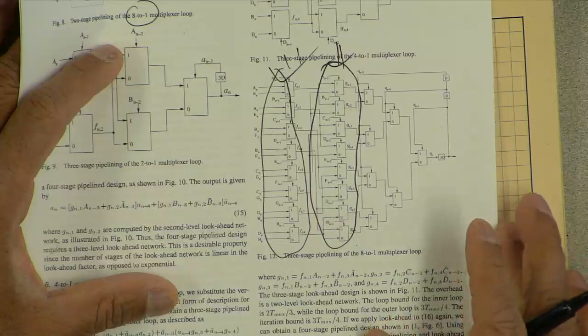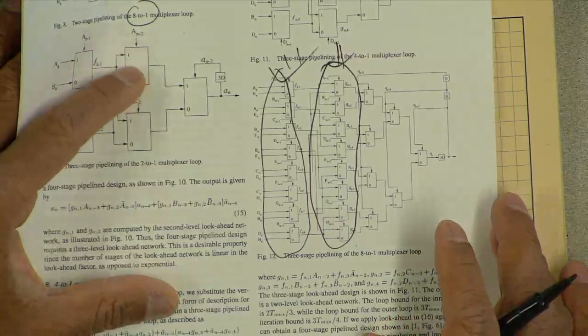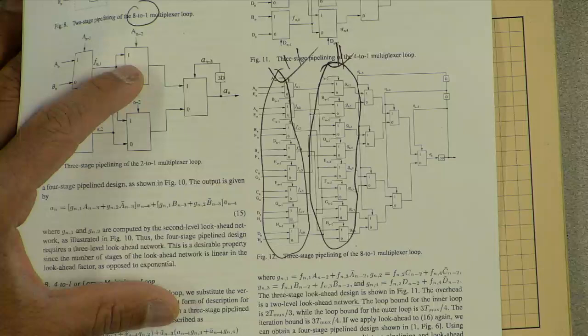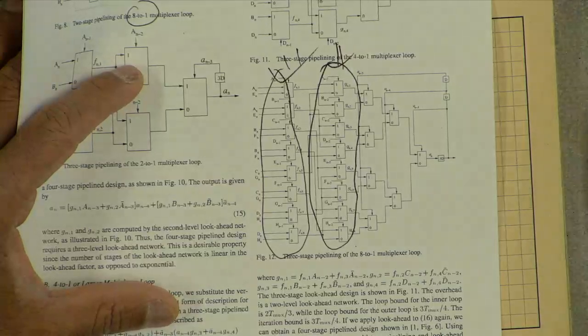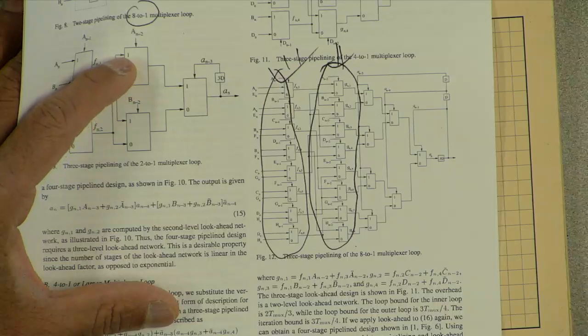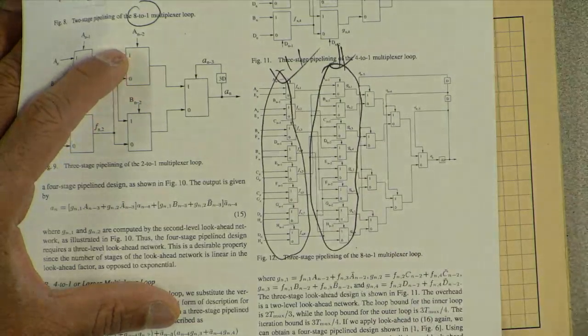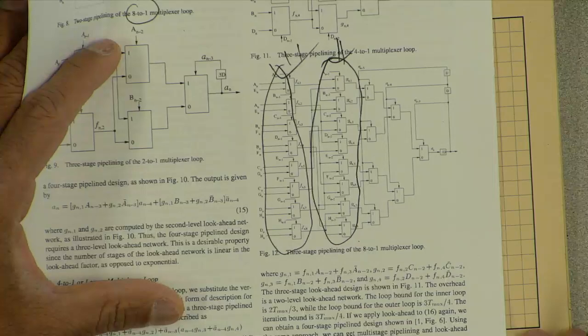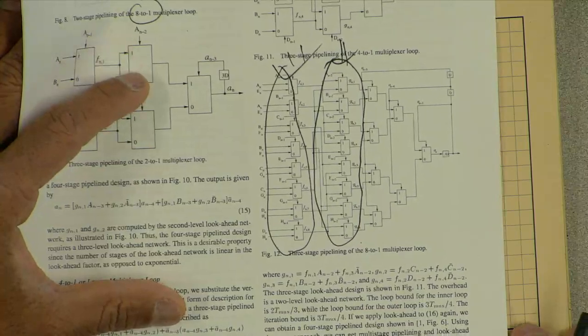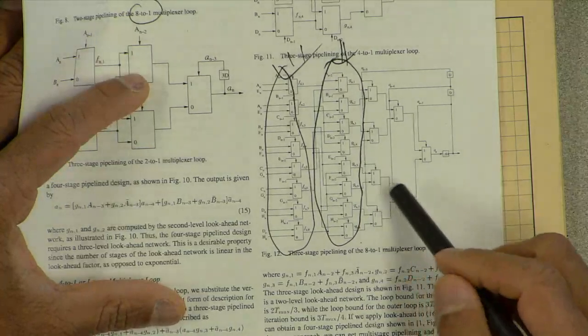So those are some ideas for how the decision feedback equalizer can be pipelined and processed in parallel, because ultimately these have to be unfolded and processed in parallel to achieve the true speed up, because the true speed up is not here.